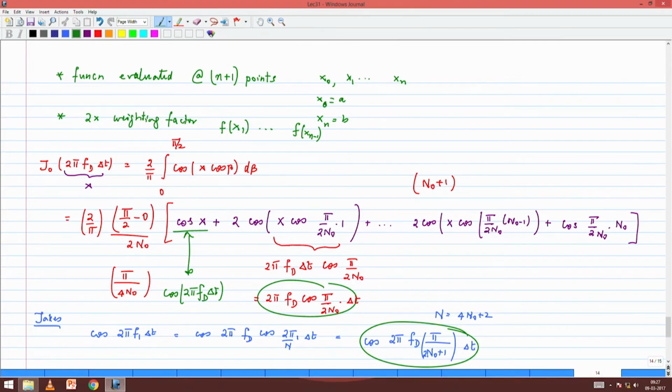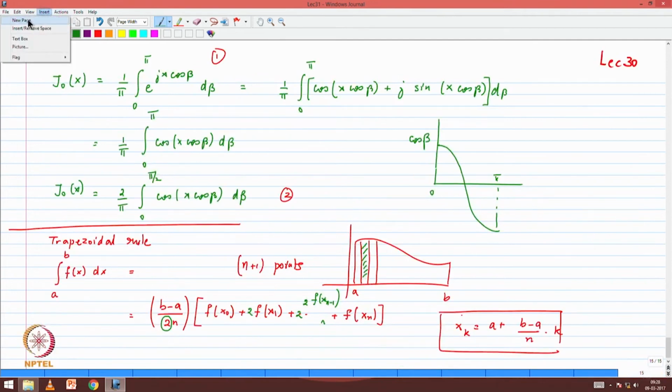All those oscillators are very closely approximated. In the trapezoidal approximation you will get 2 times n naught. In what Jakes has used, you get 2 times n naught plus 1. Again, why did he choose that n naught plus 1? Probably some other reasons we don't know. This is how he had chosen it, and we find that it's a pretty good approximation anyway by the trapezoidal rule.